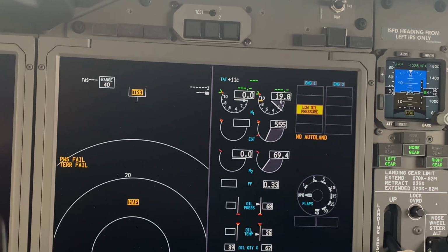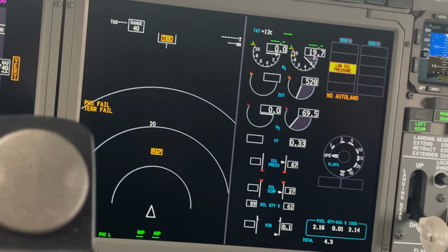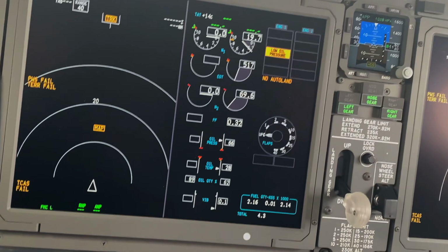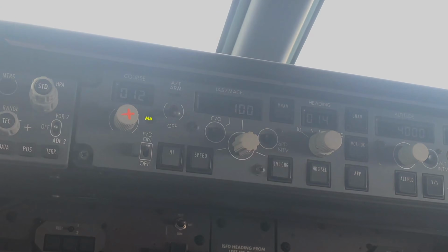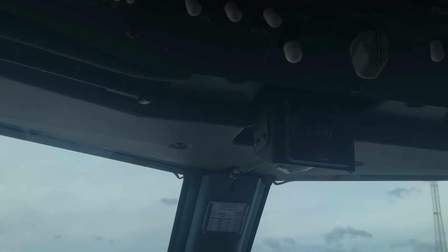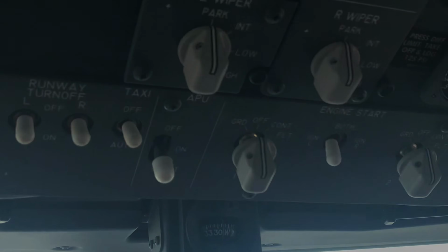The acceleration should not slow or stop before the idle speed. We use the rule: as long as you can count the digits, it's looking good. If it starts to become blurred or slow down, something's not right.